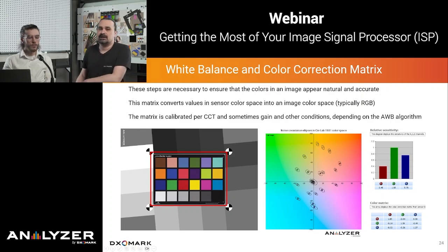The color rendering, it's a whole matrix. Why is it a matrix? It's a 3x3 matrix. You have an RGB input and an RGB output. The RGB input is the sensor RGB, the actual values in the raw file that represent the filters of my sensor, whereas the output RGB is the standardized RGB, for instance, sRGB. And I have a system of linear equations to move from one to the other, and this is represented with a matrix. This also goes with the white balance and therefore goes with the color of the illuminant, the temperature of the illuminant. So we do both of them, right?